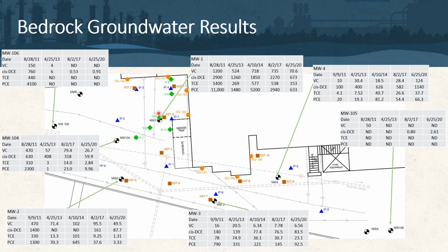And we can see from periphery wells as well here, MW2 at the creek, at the edge of the creek, looking at ppm concentrations coming down from the initial sampling down to low-level ppb concentrations, nearly meeting the MCL in cis and vinyl chloride. Next slide, please.